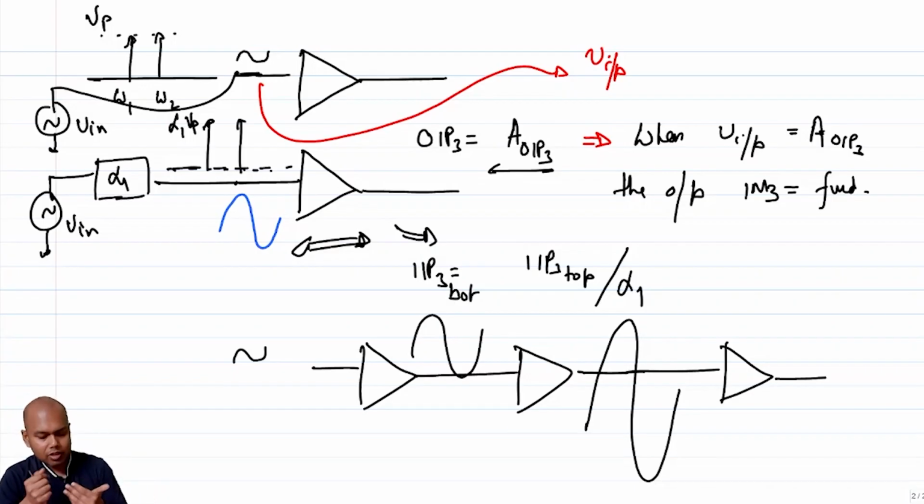So it is not sufficient only to say my IIP3 is this. Just like P1 dB, you also have to say that given that IIP3, my gain is this much, right? Without these two pieces of information simultaneously, just quoting that number does not make too much sense.